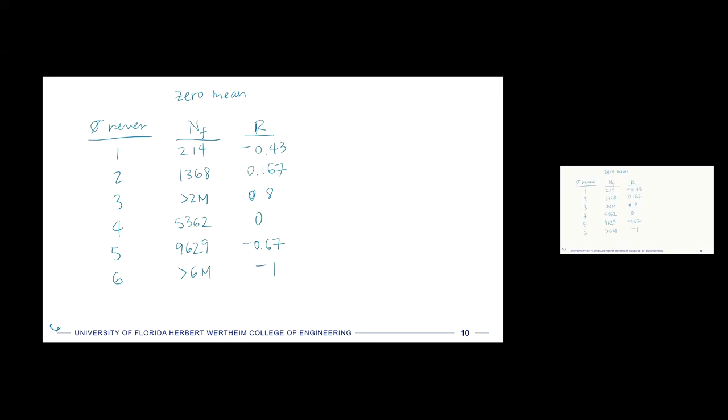And so if we use that new equation, NF, where we have a non-zero mean explicitly built into the expression, we get some slightly different numbers. 248, 1100, 15,690, 2456, 3292, and 19,065. So if we compare these two columns, you can see that for this high strain, the very first cycle